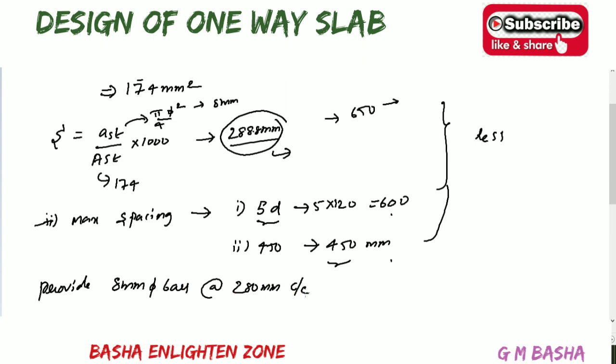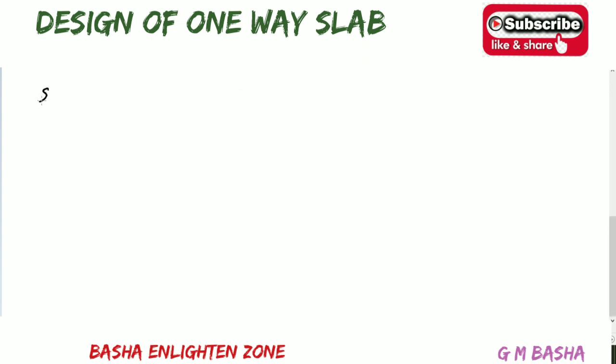And what about the shear? So your next topic is about the shear. Generally we find shear reinforcement for beams, but slabs are generally safe in shear, and hence this check may be omitted here. So therefore no need to find the shear reinforcement. Why? Because almost all slabs are safe in shear. And coming to the deflection, we are following the step by step procedure, and each and everything according to our IS, so almost our slab will be safe in deflection also.